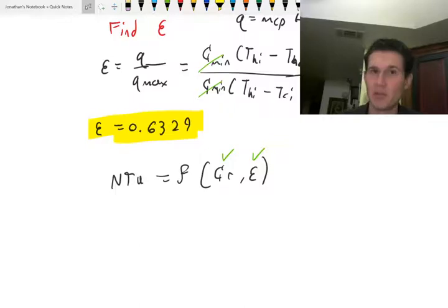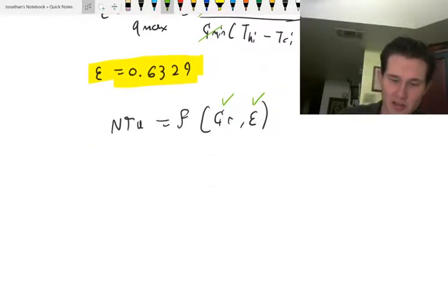All we're really doing here is we're having a shape factor for our heat exchanger. Heat exchangers have complicated geometry. Sometimes they have fins on them. Sometimes they have little things inside them to give them secondary flows to transfer heat better. But essentially, all these NTUs and efficiencies do is they give us another way to solve the problem from experimentation using a shape factor. That's really what they represent. They're just taking a complex problem, they're making one condition and giving you an approximation for this type of heat exchanger, what the numbers are going to come out like. They're just there to make your life easy.